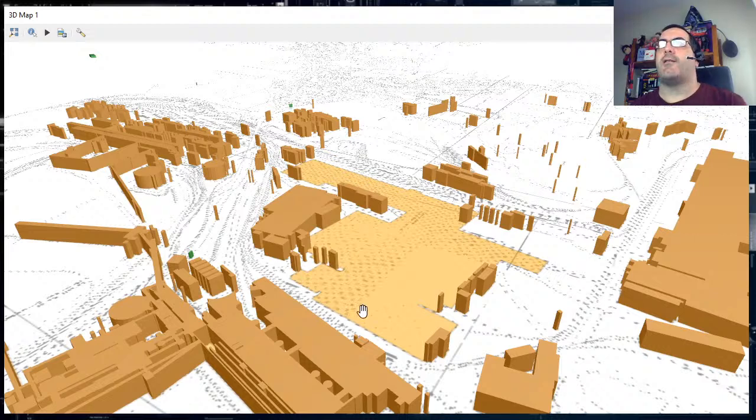because the reason this hasn't popped up with the rest of them is because there are errors in this line work somewhere. Now, we haven't actually got time at the moment to go hunting them, but my guess would be round some of these little areas here where we've got smaller buildings in between the larger ones, there's possibly some lines from this one that have got joined onto them when they weren't intended to.